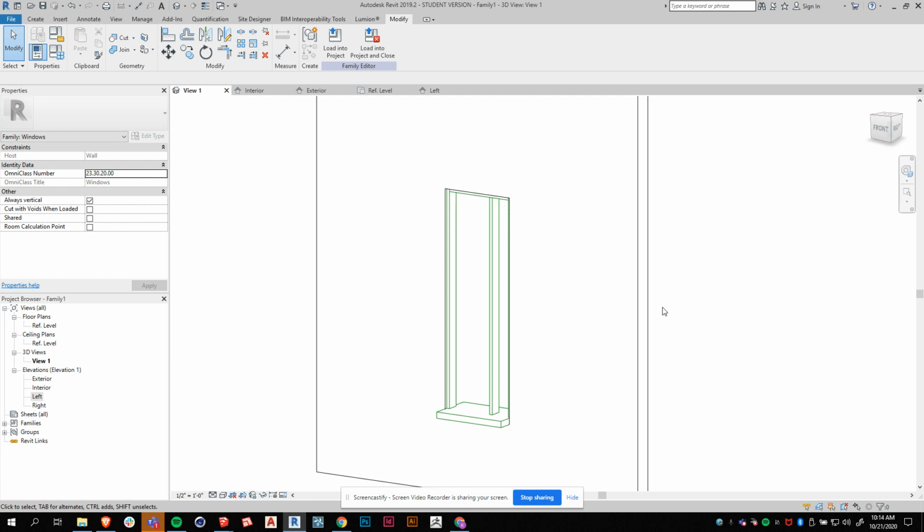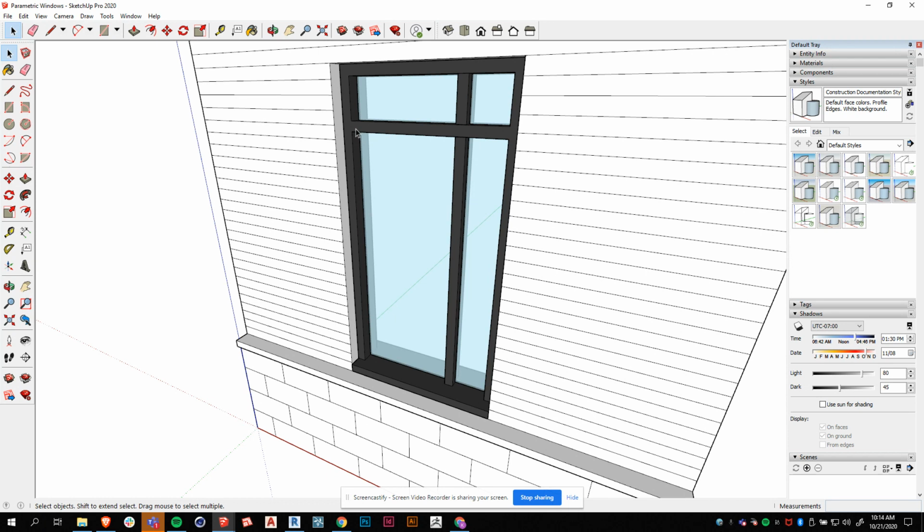Okay, there's 2 more pieces to add, and I'm going to do them on my own, but I'm going to let you guys run through it. So what I want you to add, where's my SketchUp? There we go. Is this piece. We're going to put that in that frame piece exactly the same way we did this frame piece. And then add the glass in the middle. And the glass can have a thickness of, say, 1/4 inch. Okay. So I'm going to hit pause on this video. I'm going to do that. And then I'm going to show you how to bring it into a project.